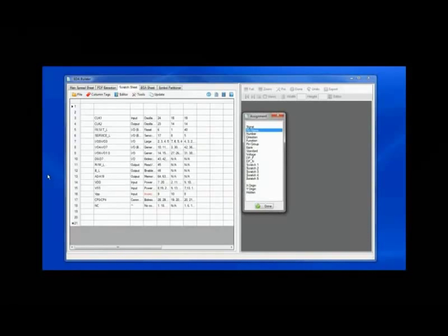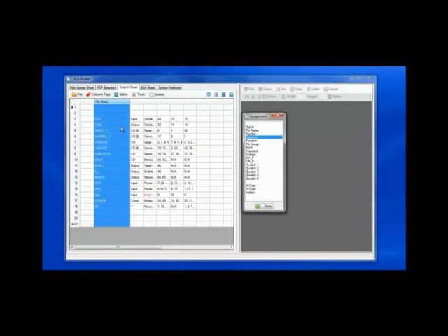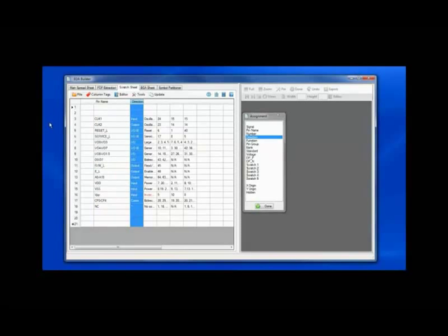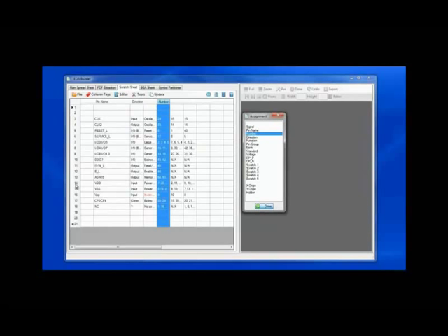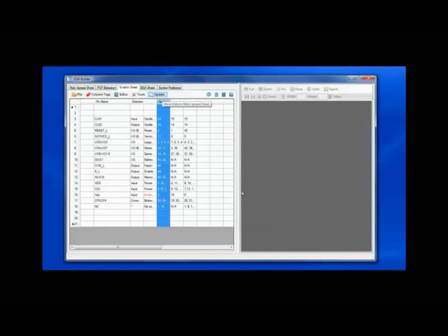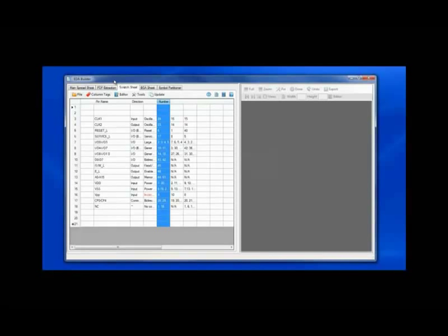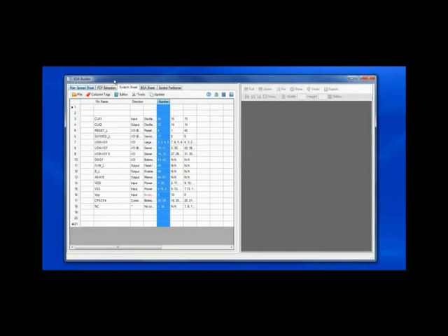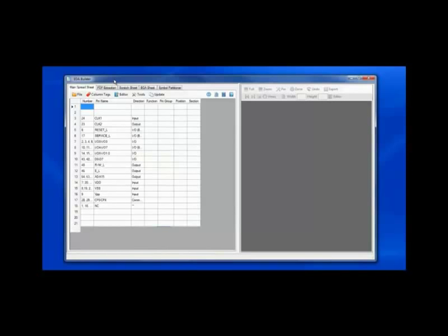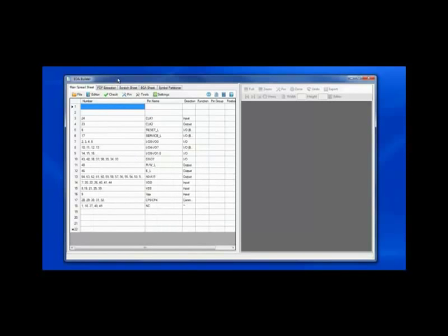I will now tag the individual columns, in this case, pin name, pin direction, and pin number. In the previous case, where we were modeling the PCB footprint, we had X origin and Y origin. Let's take the table now and copy the content to the main spreadsheet. Bringing up the main spreadsheet, I now have the pin numbers, pin names, and pin directions.